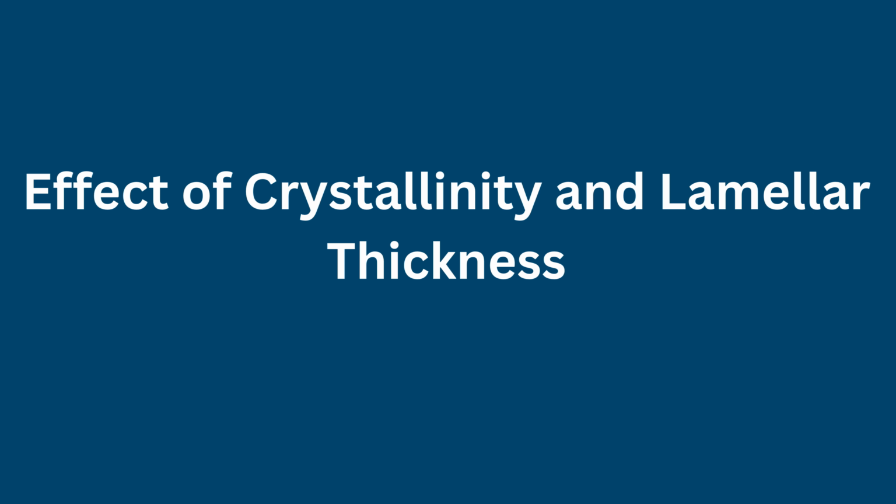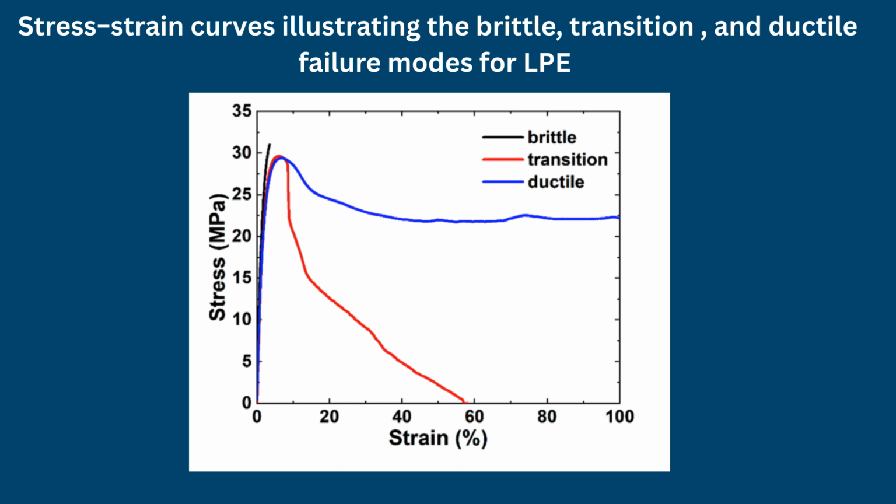Effect of crystallinity and lamellar thickness. Increasing crystallinity generally increases modulus, yield strength, hardness, and dimensional stability because crystalline domains act as rigid reinforcing structures.